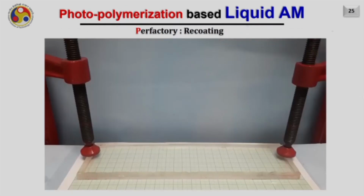So there are two methods for recoating the layer in the case of the top down approach. One is that we lift the substrate and then allow the liquid material to come under the built part, or we slide the object away and then allow a new layer of the liquid photopolymer to be available under the layer. Of these two methods, definitely the sliding is better, as we have just said.